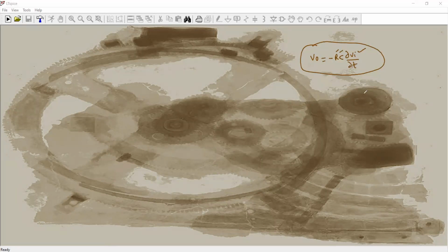So we will actually have a kind of circuit. As you can see, I'm going to draw that. So you will have an amplifier that has two pins. It's a differential amplifier, and then we have the output. We'll have the capacitor at the input circuit, and in the feedback path we will have the resistor R. This is C, and here is your input signal Vi that will provide the input current Ii, and the positive input is connected to the ground.